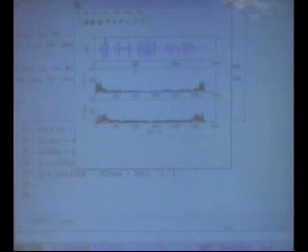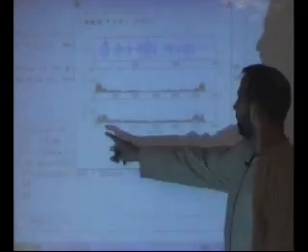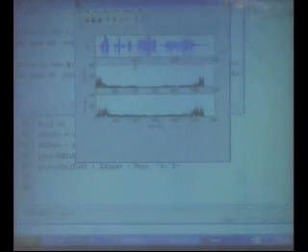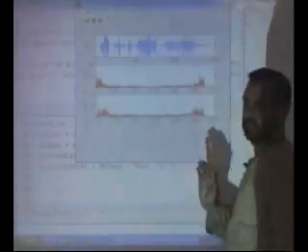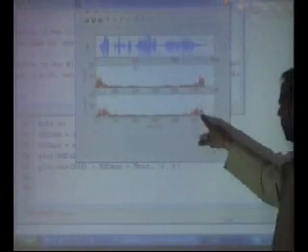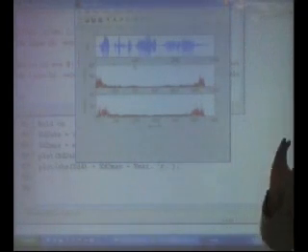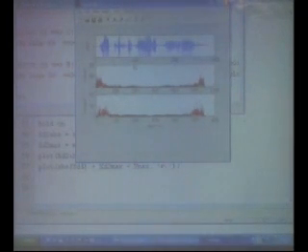So then what you do is you downsample. What you see here is a downsampled version where I'm throwing away every other sample. A downsampling means that the spectrum, though it is shown on the same scale, will expand. So it really means that you cut it down from here and move it, but then I'm just changing the axis, but I'll show you on the original scale as well. I'll keep the scale as is, and I'll show you what is happening to the spectrum.